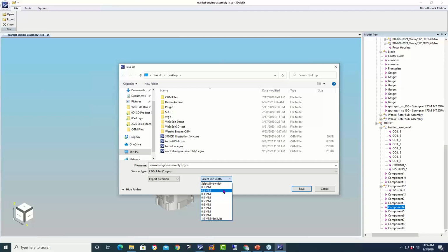If you're looking for thick and thin, it's not something we're doing automatically at the moment. But once it's through into VXEdit, you can apply line widths in there to selected lines. If you've got thick and thin, you could create it in there quite quickly. That's why we wanted this link to VXEdit: we still believe you're going to have to finish the illustration off by adding hotspots or annotations or changing some line weights. So you've still got that connection between the two.